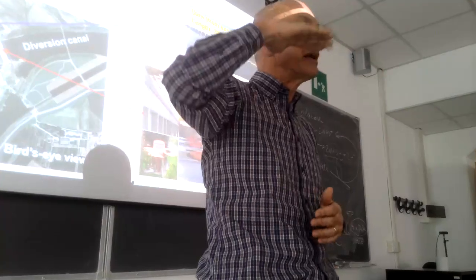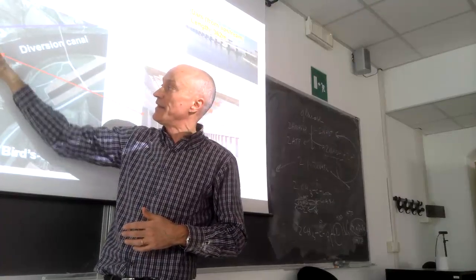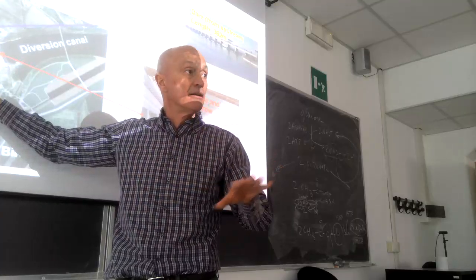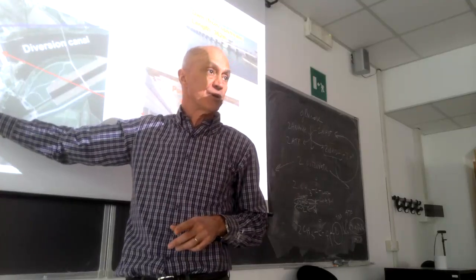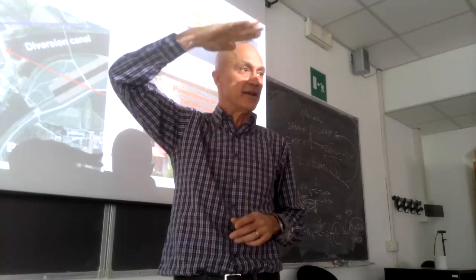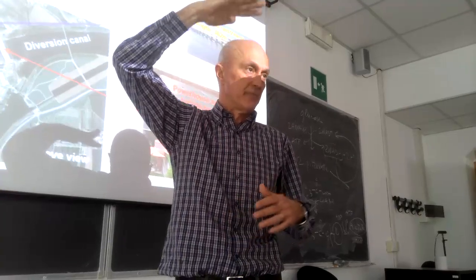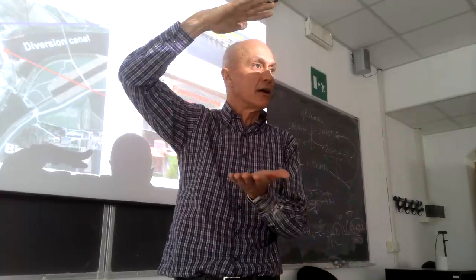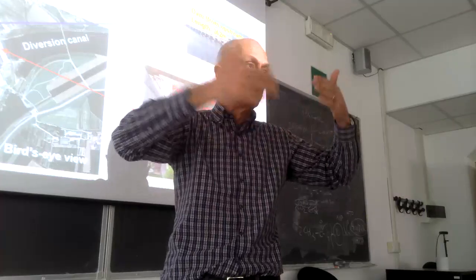So when the discharge is high, the water level is high on its own, but when the discharge is low, the water level will go down. Controlling the gates in the dam, they keep the water level high. The water level is what governs the hydraulic head between the intake and the tail water. Okay?